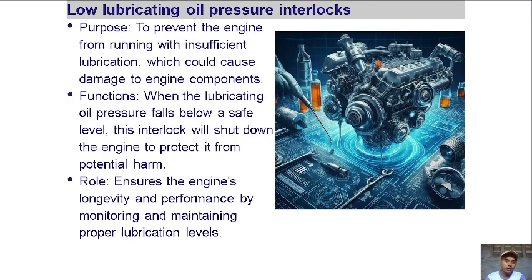The function: when the lubricating oil pressure falls below a safe level, this interlock will shut down the engine to protect it from potential harm. It ensures the engine's longevity and performance by monitoring and maintaining proper lubrication levels. At a specific low pressure alarm, it will also trigger a low pressure shutdown. If shutdown is triggered, the engine will be stopped to prevent it from being damaged due to no lubricating oil in the engine.